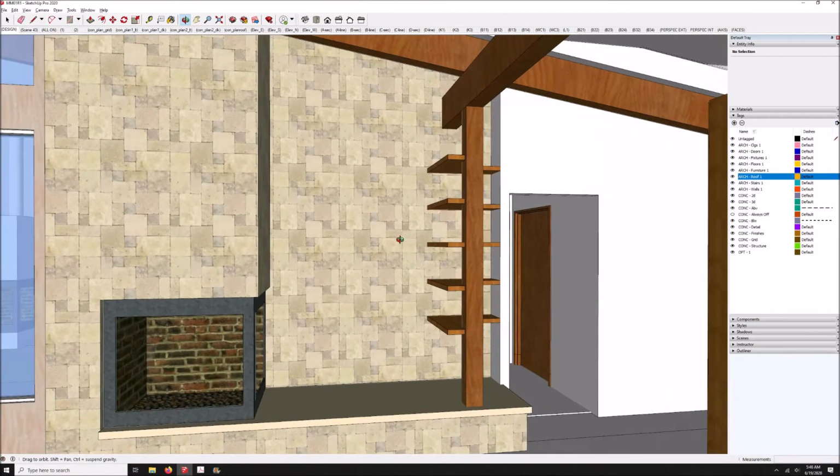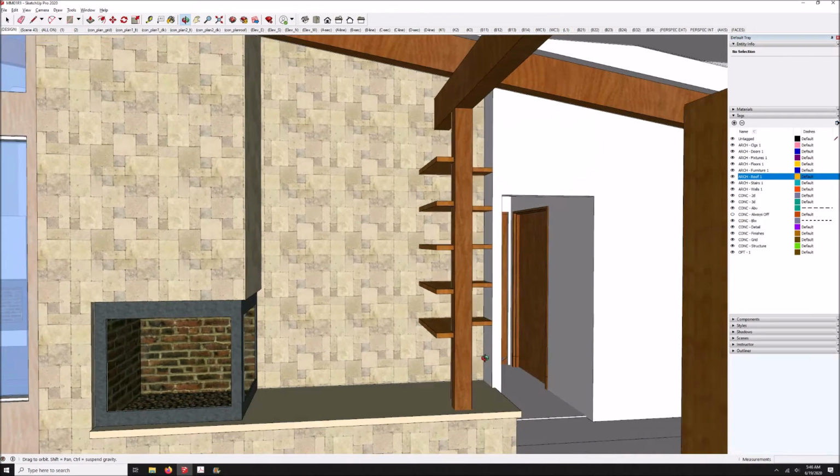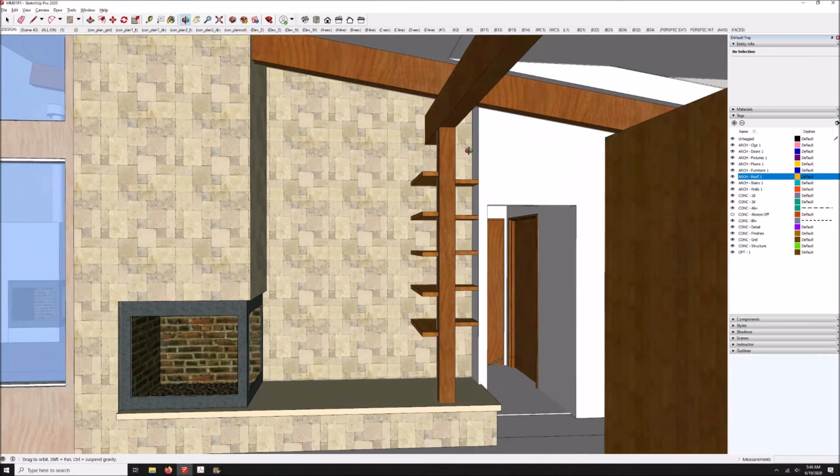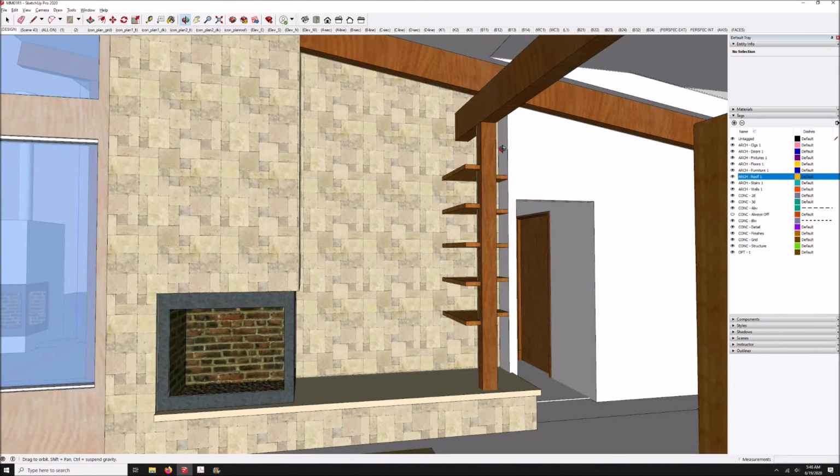And when I pushed the wall back in order to fit the fireplace in, it gave me a convenient spot to end the stone veneer. You generally don't want to end materials on an outside corner. You don't want to change materials on an outside corner because you see the edge of the material. If you can find a way to butt materials to an inside corner, you get a much cleaner finish.